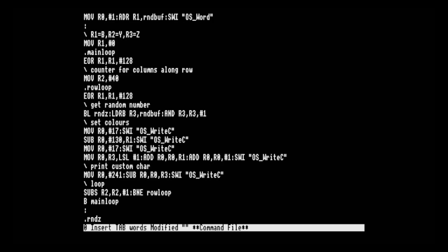Well, unfortunately not, because the only operand that can actually be an immediate value is the final one. The first one, or the second one, the number you're subtracting from, that always has to be a register. So I could put the R1 there and then leave the 130 on the end, but then the problem is I'm doing the subtract in the wrong order. So instead of subtracting R1 from 130, what we're now doing is subtracting 130 from R1. But that's actually okay, because there's a special version of the subtract instruction called reverse subtract, and this uses the operands in the opposite order. So this one will take the third operand and then subtract the second one from it and store the result in the first one. So this will do 130 minus R1 and store it in R0.